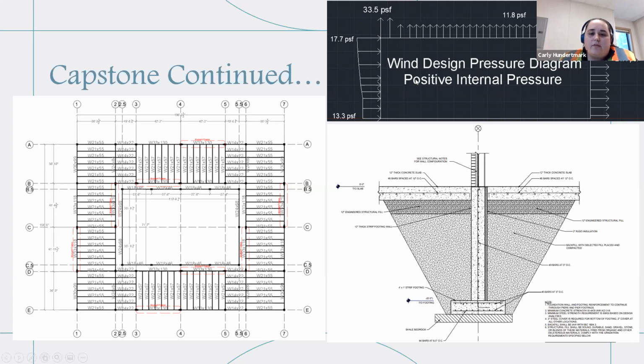So this is kind of cool. Whenever you look at a building, you actually have to design for different types of loading. So different types of pressures coming from earthquakes, wind, environmental loading. So snow, if you're in a snowy area, you have to account for that, make sure the building can handle it and hold it up. And so this one is actually a wind diagnostics of our building and how, if wind was pushing on it, what would end up happening, what members were getting crunched together, which is in compression, or being pulled apart, which is tension.